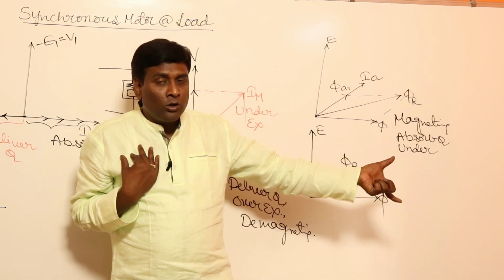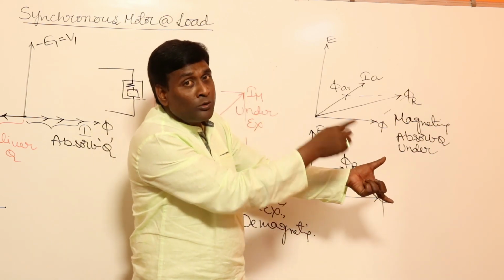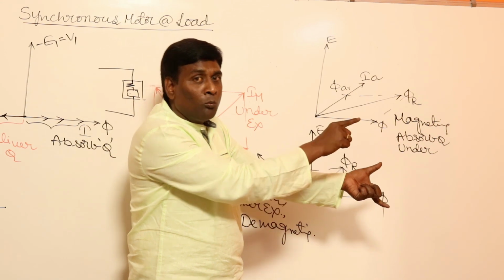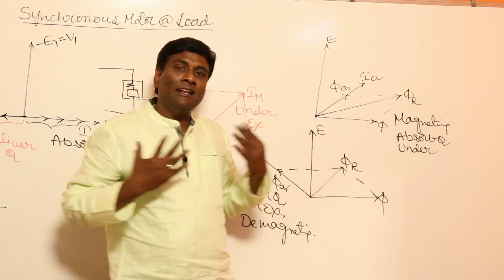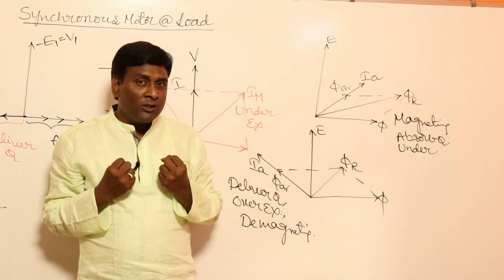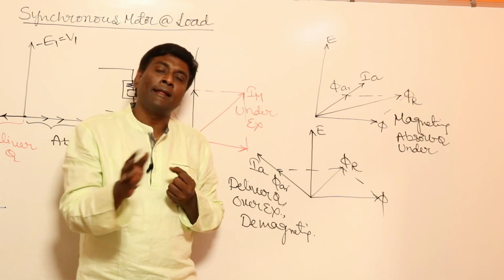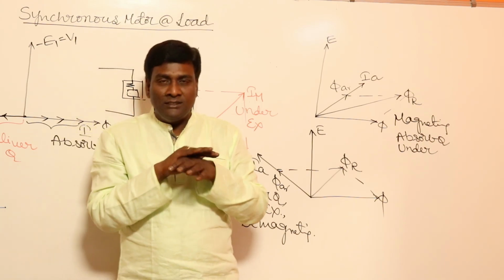When a motor absorbs, it should have inductive dominated effects. So a motor absorbing at lagging, and a generator operating at leading, absorb reactive power. Both should be underexcited. Okay, so this is the conclusion.